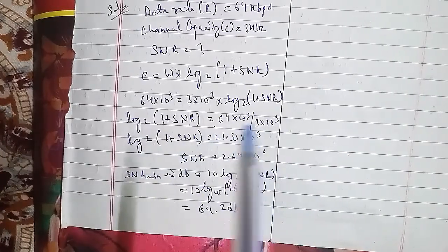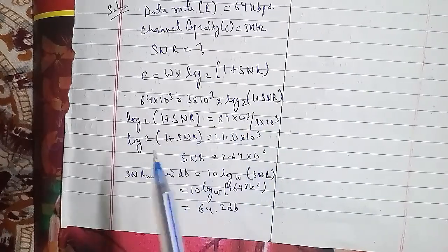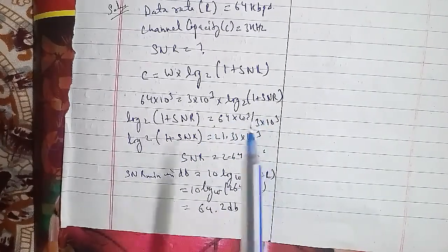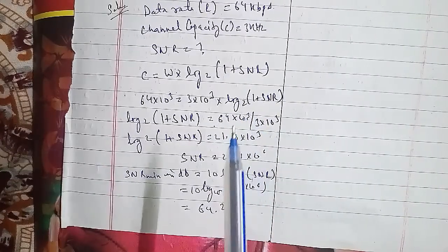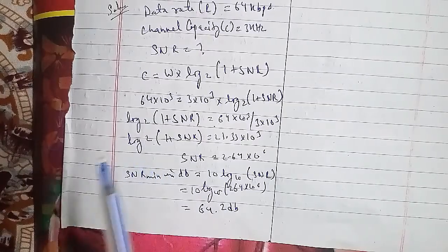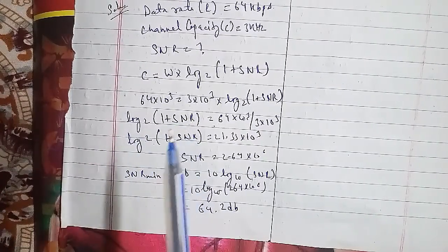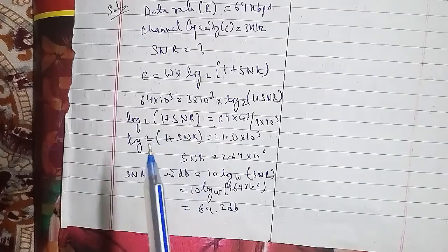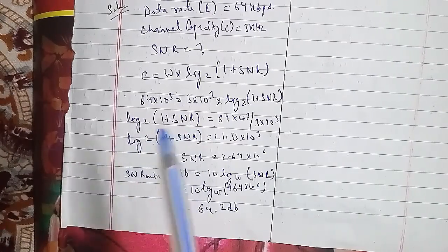To overcome this problem, techniques are available for equalizing the attenuation across a band of frequencies. This is commonly done for voice-grade telephone lines by using loading coils that change the electrical properties of the line, which smooths out the attenuation effect. Another approach is to use amplifiers that amplify high frequencies more than lower frequencies.